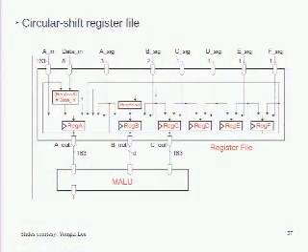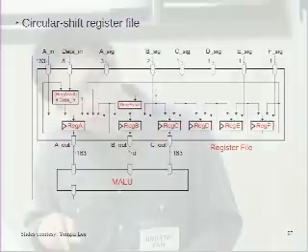And to further reduce the hardware cost, you can also simplify the register file architecture. I guess this is probably not so interesting here. Basically, for a normal register file, you can access every register from outside. And in this one, you can only access A, and if you want to put something in C, you first put it in A and you shift it. So you somehow simplify the interconnection, which also reduces the area. So that's the trick we played to reduce the hardware, the area.